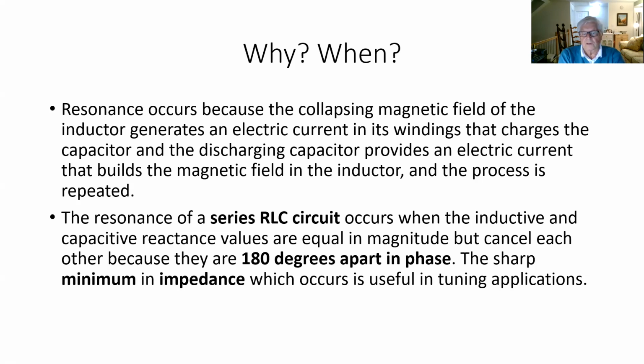Basically the net reactance is zero, which is equivalent to zero resistance. So the impedance is a minimum, and that is what we can use in a tuning application.